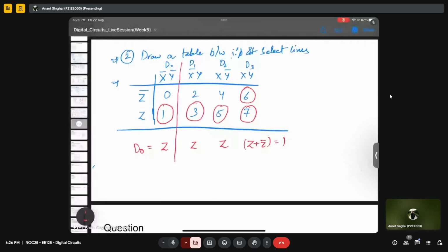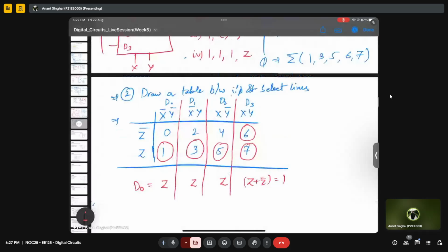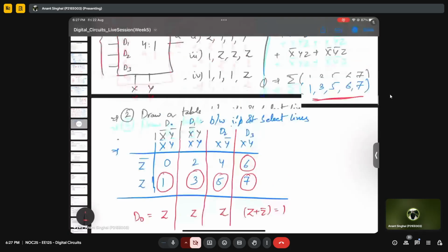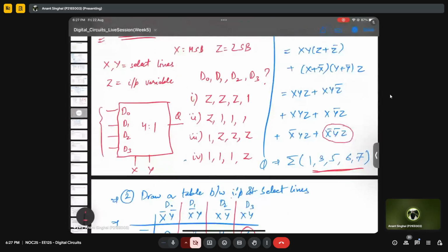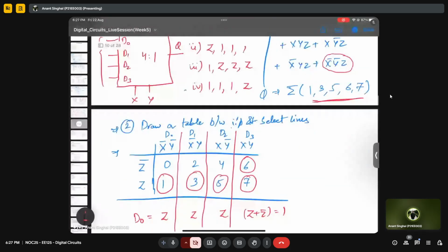No, it's not a Karnaugh map, it's just a general indication of these terms. I wanted to see what I need to multiply to actually get the final answer, because my input expression had x bar y bar z. So I've written x bar y bar and then z, and here it is 1. And there is no x bar y bar z bar, so I just need to multiply the input by z, not by 1.